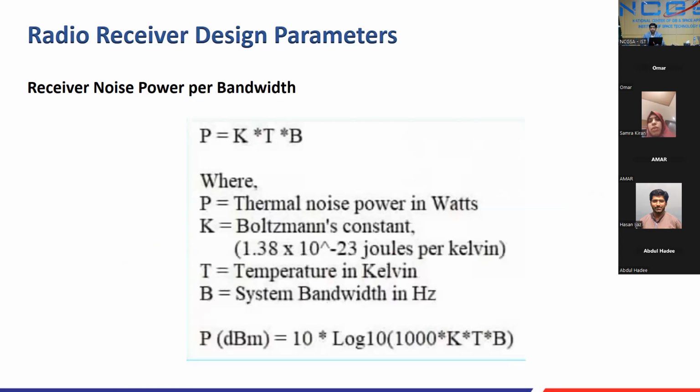Now, for any system, architecture or receiver you are making, the customer or end user will be asking you about the available bandwidth, and the bandwidth you need to offer contributes directly to the noise figure of the receiver. The generic, famous formula kTB: noise power equals Boltzmann constant, times the system temperature, times the bandwidth. For the system temperature, in general calculations we usually use 315 Kelvin. It's a good assumption. And then you have the bandwidth. So there's a standard that for 1 hertz of bandwidth, the noise floor is around minus 174 dBm.